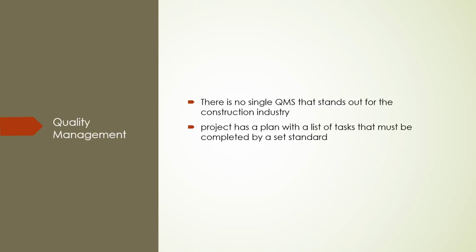For example, soil compaction, strength of concrete, and welding are traditionally checked or tested by a third party. These tests are conducted during the execution of the work, and the quality of the product is determined and reported shortly after the tests or inspections are made.